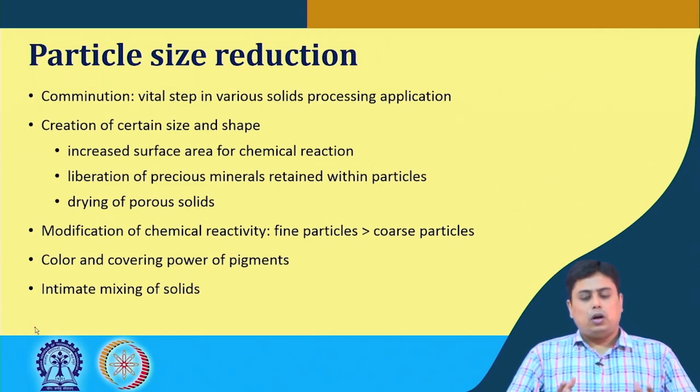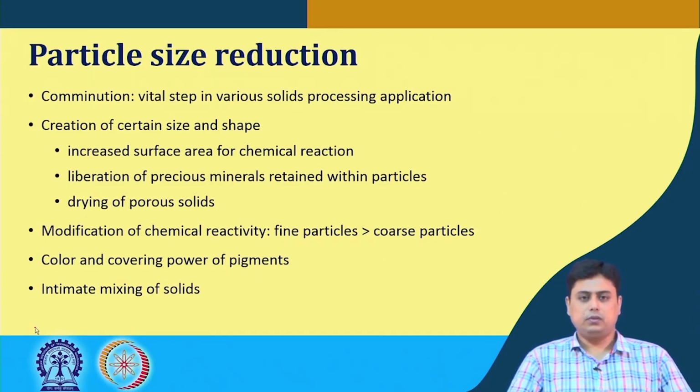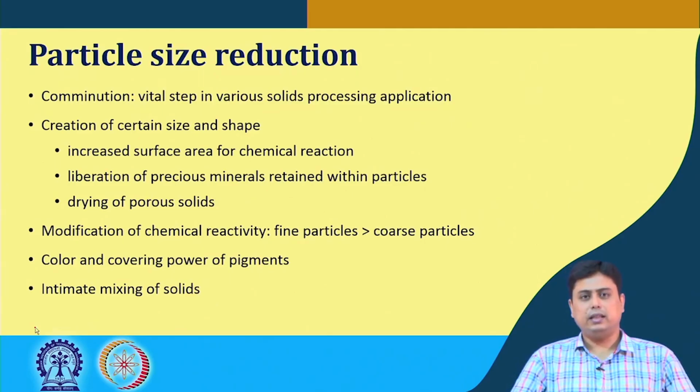So, all these benefits of size reduction are there, but a certain point has to be remembered: if we modify the surface to a great extent or reduce the size to a greater extent, then there are chances of modifying the chemical reactivity of that solid particle, and this reactivity is higher in fine particles than in coarse particles.